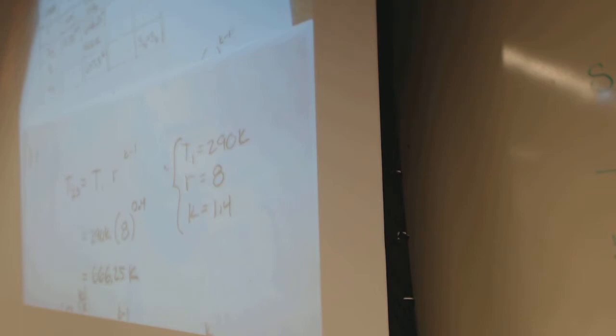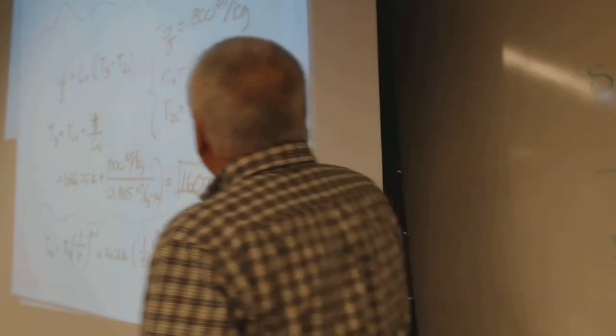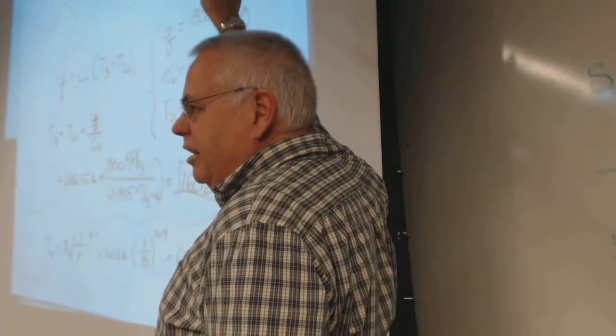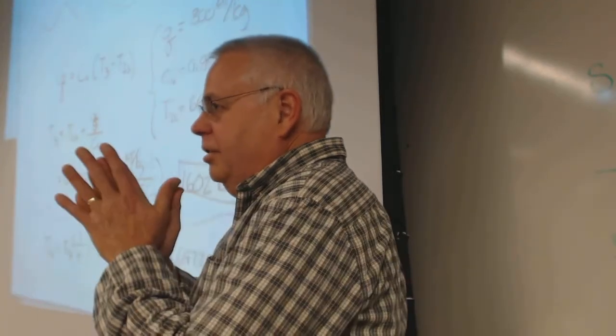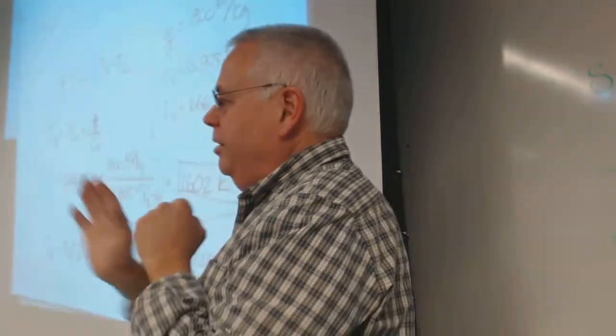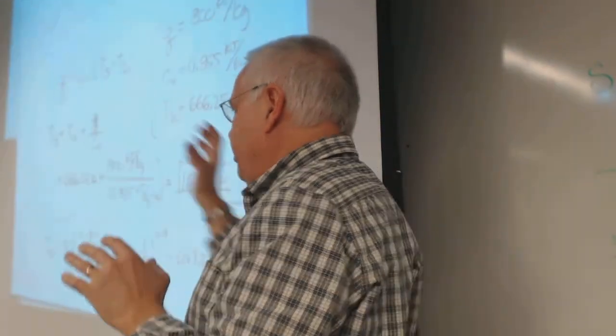Now we're starting off in our table. Let me bring that back up so you can see. Started off at 290 Kelvin. Went up to 670 Kelvin just from the compression stroke. Added fuel, went higher pressure, and now the difference in pressure between when we pushed it and when it expanded